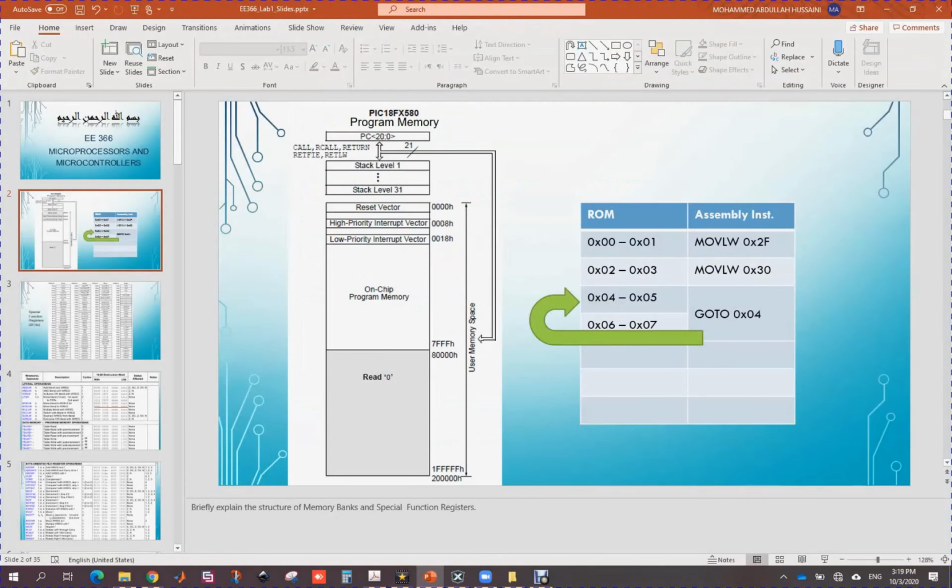So go to $ sign is to tell the microcontroller to simply go to the same location on which this instruction is stored. So it keeps on jumping to this location. So either you can write the location number, or you can assign a label here, or you can simply say like this. So it keeps on jumping to the same location. That means it keeps on executing this instruction. So this is like an infinite while loop which simply jumps to the same location. It tells the microcontroller to not execute anything after that.